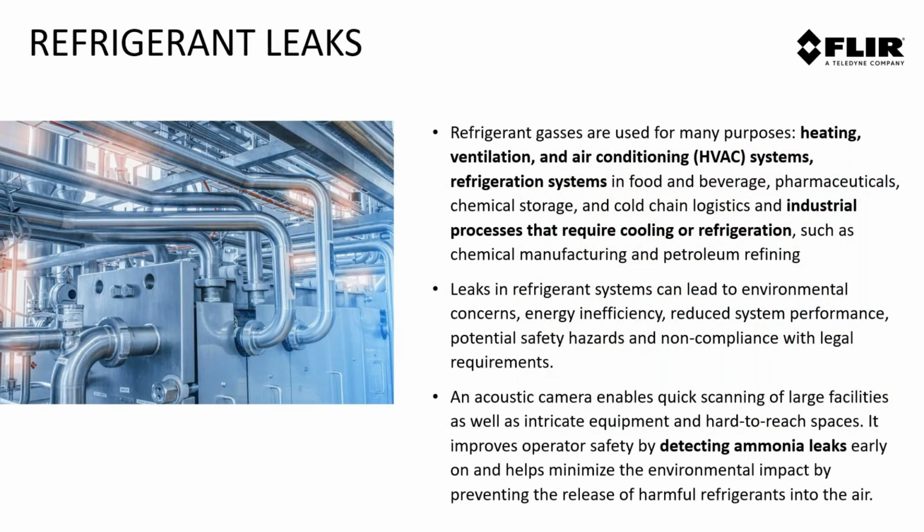Another key area is on the refrigeration side. Obviously a lot of refrigeration systems, food and bev, pharmaceutical facilities, they're all out there. Any industrial processes that require that heavy cooling or refrigeration, be able to identify refrigerant leaks as well. The camera can scan large facilities, detect ammonia leaks, depending on the pressurization of those leaks early, and minimize those environmental impacts as a result of being able to have a proper inspection and scanning program with this tool.